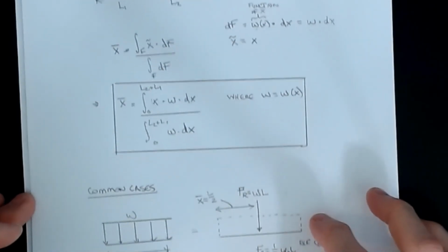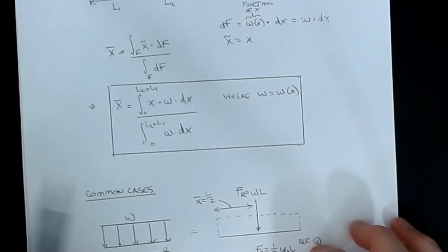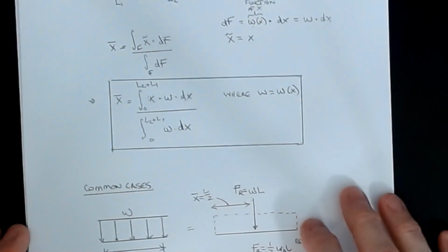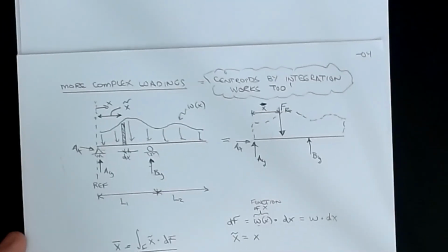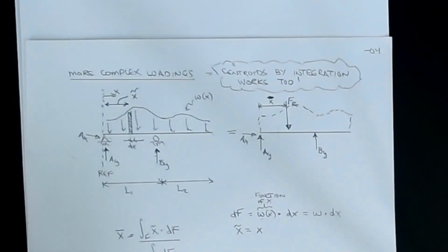It's exactly like the integration method. So if you're struggling with that, go take a look back at our last video where we walked you through in more detail how you set this up. It's exactly the same approach, but now I've got the ability to handle not just uniform loads, but any load, as long as I can define the load as a function of x.